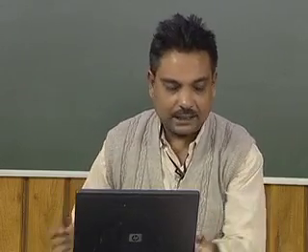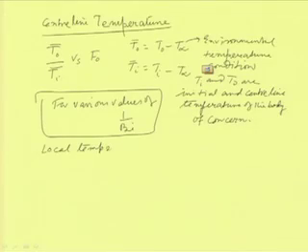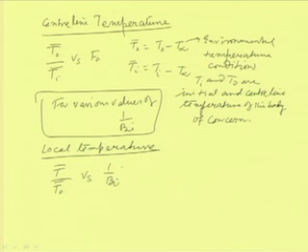Any local temperature is also calculated as a dimensionless temperature, with a plot of this versus 1 by Biot number. So we can understand why in the very first case we need the center line temperature: once we know it, from the center line temperature expressions we can find the dimensionless reduced temperature at any location.